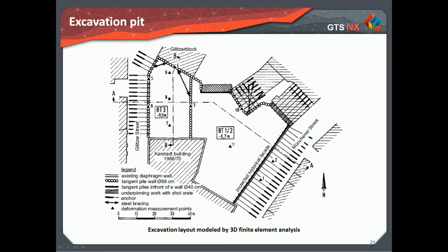Most basement excavations are three-dimensional in nature and require some degree of idealization to two-dimensional plane strain to render them solvable within realistic turnaround time on existing computing platforms. We need to consider carefully what is the effect of such idealization on the solutions.